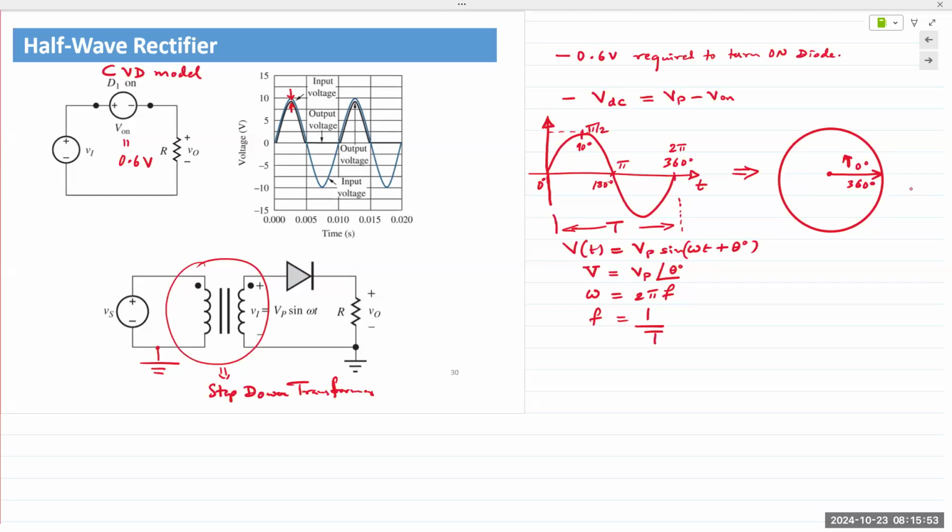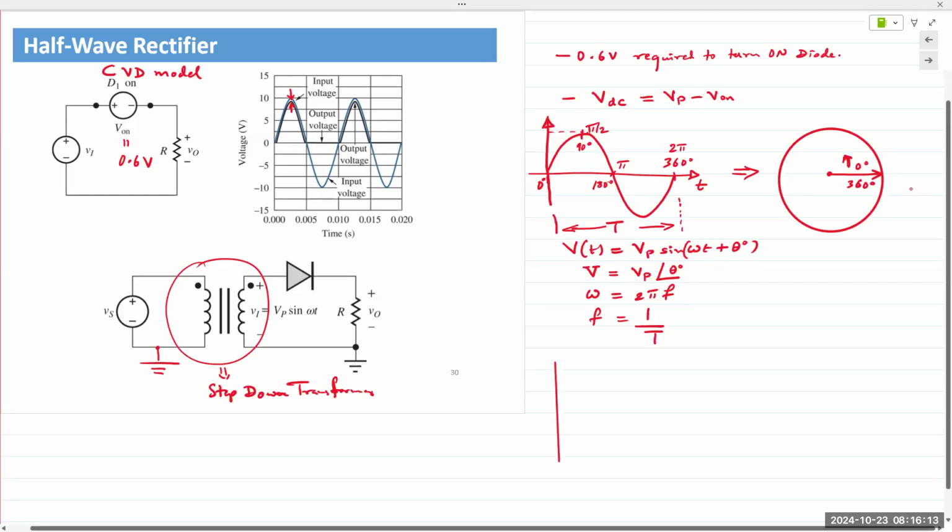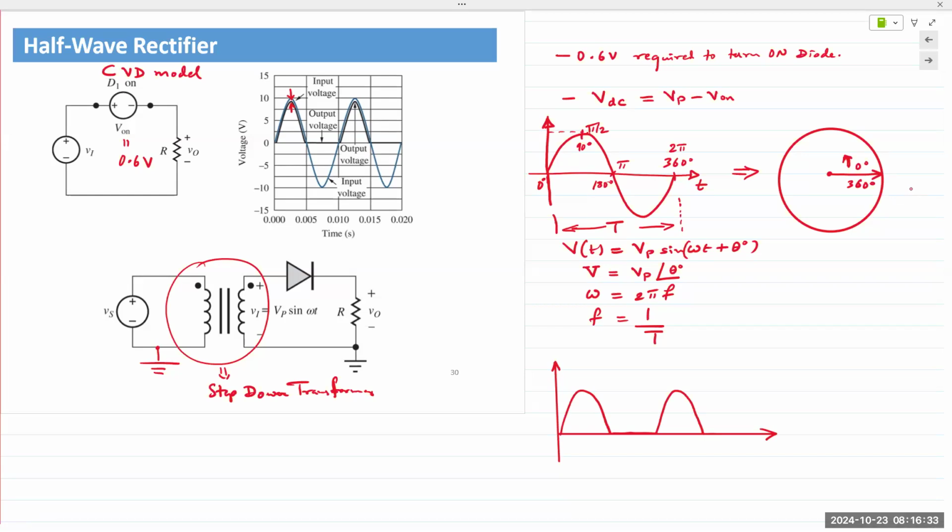So now when we apply our sine wave, we just saw that a little bit of the voltage is required to turn the diodes on. And of course, this is not quite a full flat line, right? I personally like to call it both AC as well as DC, because the value of the waveform is constantly changing with respect to time. So the output waveform, even though we refer to it as DC, still has values that fluctuate with respect to time, right?